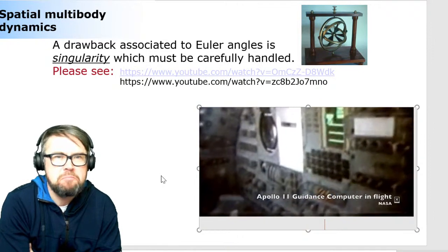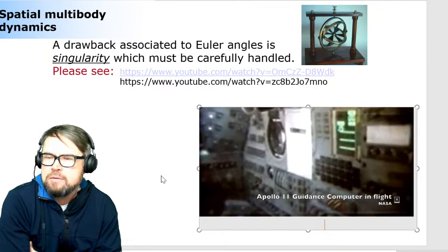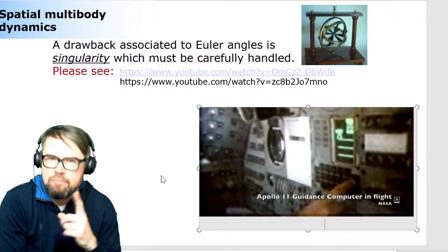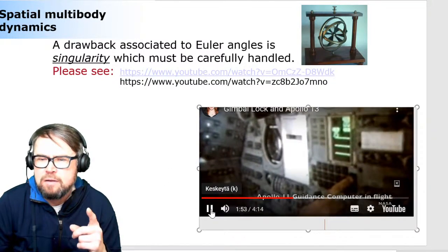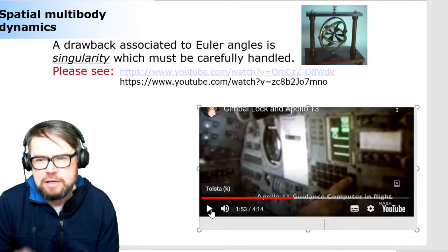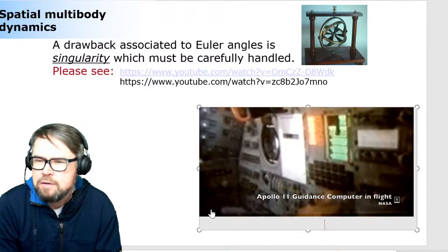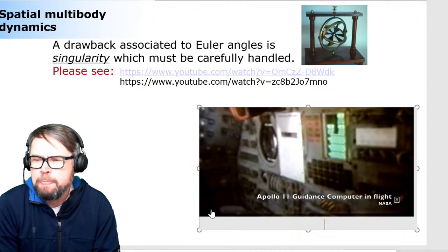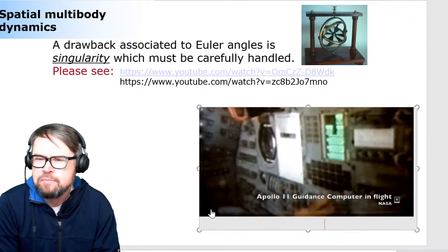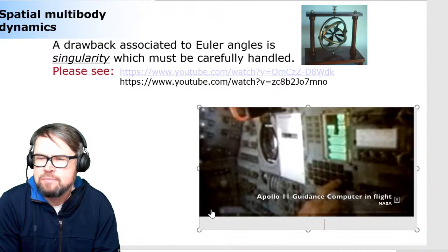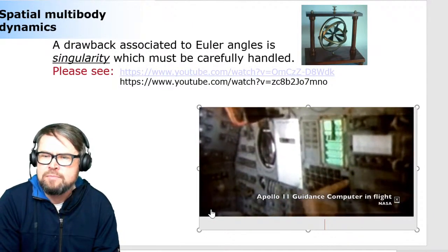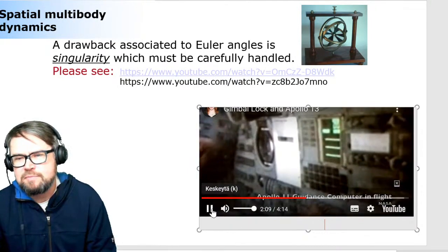The phenomenon of gimbal lock is one wherein the outer gimbal moves with the spacecraft to a point where it lies parallel to the inner gimbal. At this point, all 3 gimbal axes are parallel. So that's the keyword. They would be lined up on a single plane, and none would be able to move around the basic plane to resume a normal orientation. In short, once the gimbals are lined up, they can't realign themselves to give you an orientation, and they become locked. It's the confluence of 3 angles.